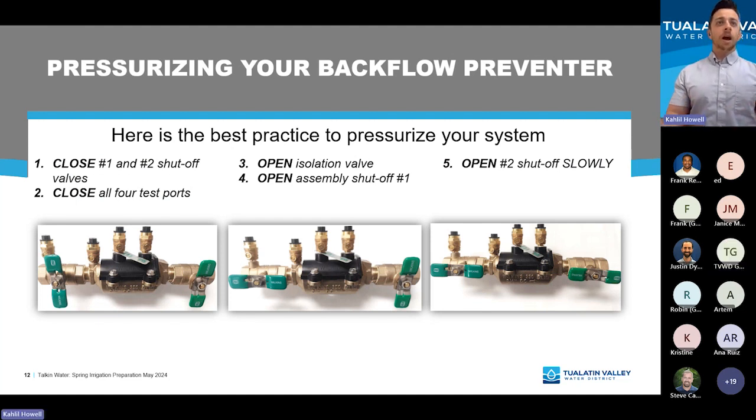An optional step, kind of a DIY leak detection, would be making sure first all our valves in our home are closed, so we have no water flowing anywhere in our plumbing system, and then going out and looking at our meter. There is often a little blue triangle. If that is at a dead standstill, it means there's no water flowing to your plumbing system.